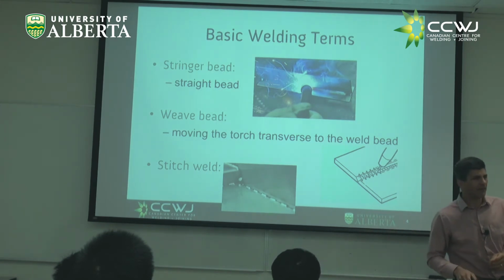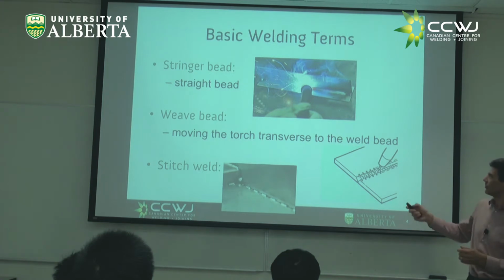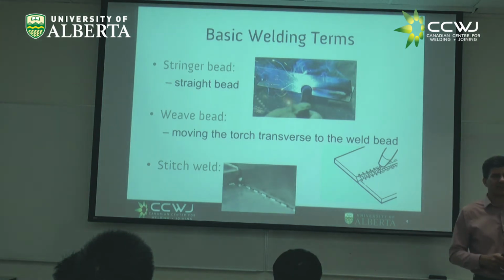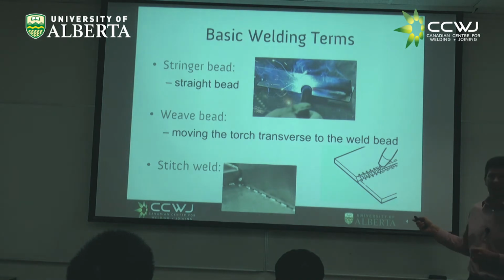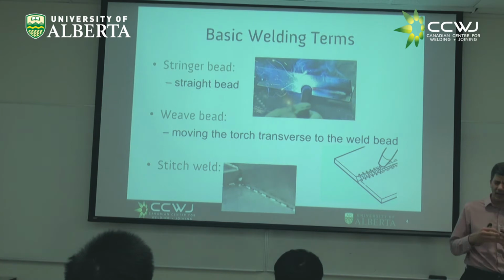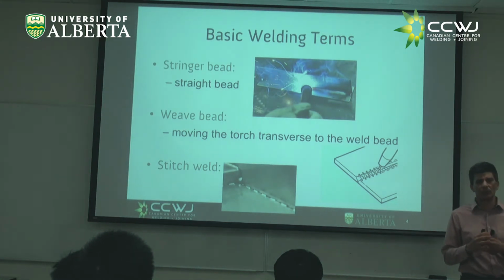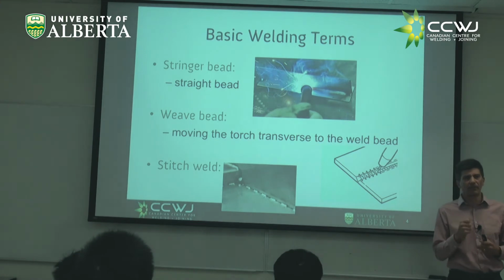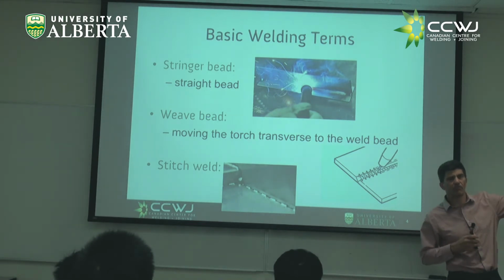So, for example, in some stainless steels, you require stringer beads. In carbon steel, very often you would do this type of thing, right? You start to see, and we're going to have formulas out of all this, how things start to come together, how decisions that the welder does out of convenience have an implication for metallurgy, right?